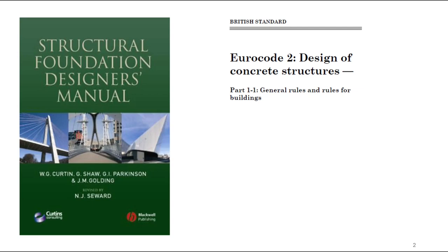It's because in such structures, rafts are much thicker, much stiffer, and usually they are modeled as one element, which is transferring loading from many columns, many walls to the soil, whereas in our software, we rather check local parts of raft under local loadings, and we treat them as sort of separate virtual foundation pads or strip foundations, and we look at those local parts independently.